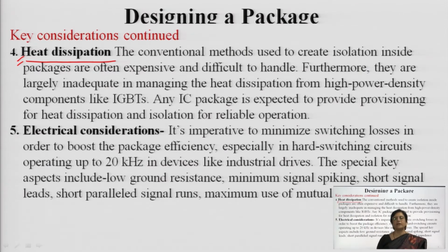Last is electrical considerations. Every circuit needs to have minimized power losses, because power will be consumed when there is switching activity, especially in the case of digital circuits. So these switching losses you need to take into account in order to boost the package efficiency, especially when you have hard switching circuits operating higher than 20 kilohertz, such as industrial devices.